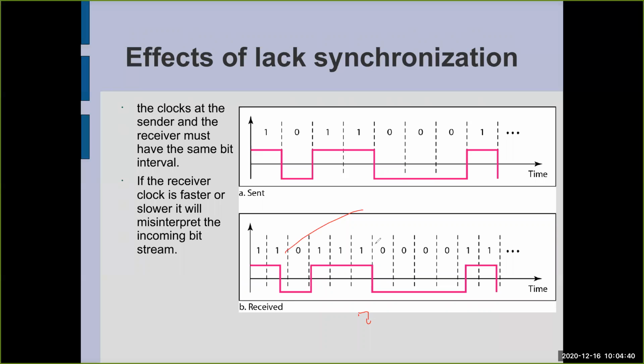But if we apply synchronization on edge, you can see that, okay, here a particular bit was found, but here, because the edge is changed, I can synchronize my counter, so 0 will start here, in this position.